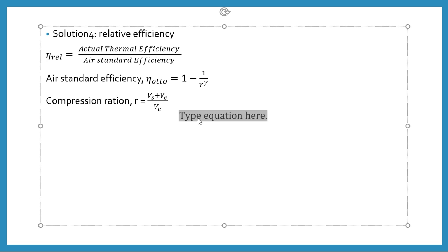So students, we know the equation of the swept volume, that is A into L. Here A means pi by 4 into d square, so pi by 4 into d square into L. Now put the values here.